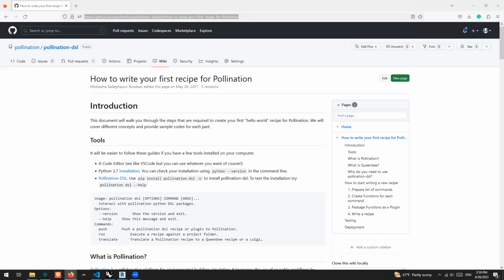The challenge with Grasshopper is that it has its own limitations. I mean, there is Rhino Compute, but I like the Ladybug bit where you can take a mass and throw a bunch of shading onto it. I guess you could bake it and then send it up to Pollination. Yeah, you can, totally.